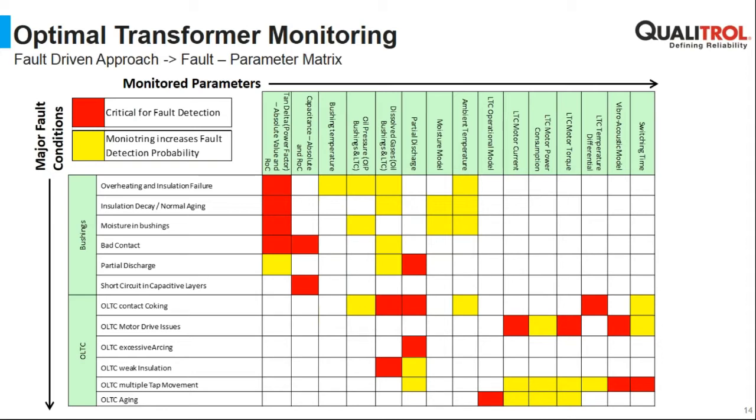And looking into the bushings, for example, if I want to detect some moisture, mainly due to maybe the sealing is not working that well on the bushing anymore, how are we going to detect that? The offline methods sometimes start to be sensitive only once the moisture has increased quite high.